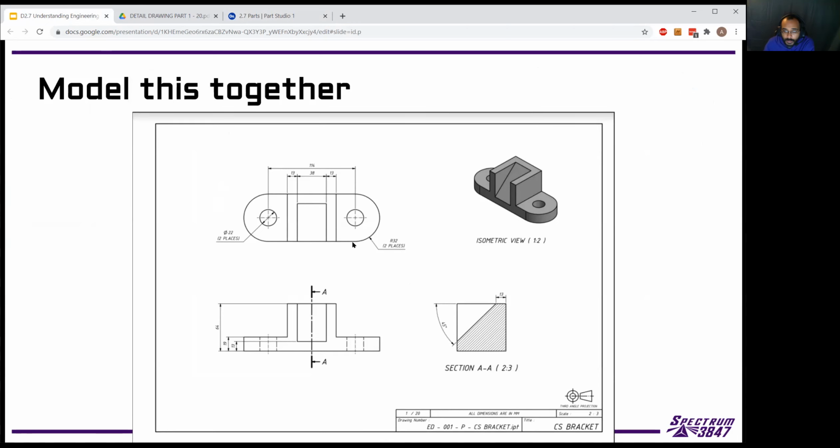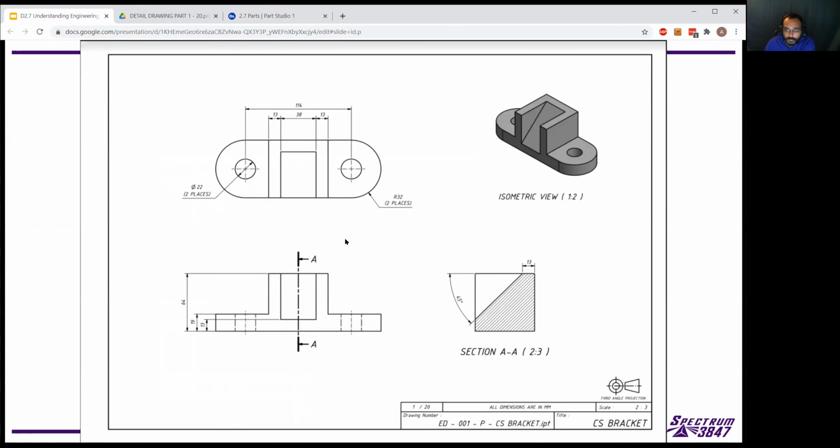So we know, I think there's a bigger set. There we go. So this is a little bit easier to see. We know that we talked about earlier, the radius of this whole rounded section is 32. That actually tells us the width of this part, because since it's not marked anywhere, we can assume these are tangent, which means this circle is basically 180 degrees. So the whole length here is 64. And then we'll have to figure out the width as well from the information that's provided.